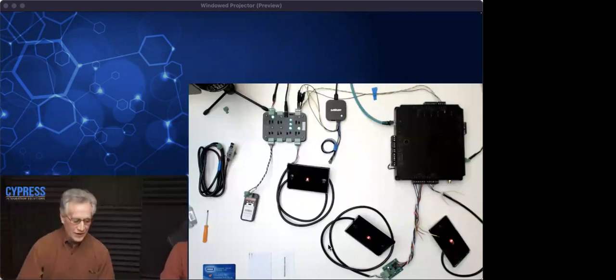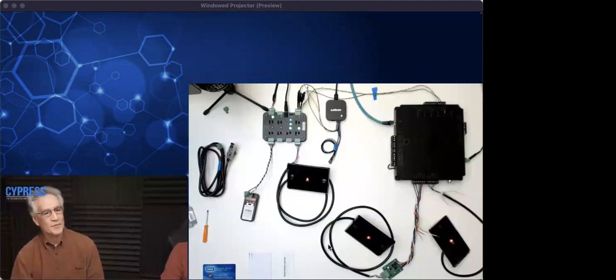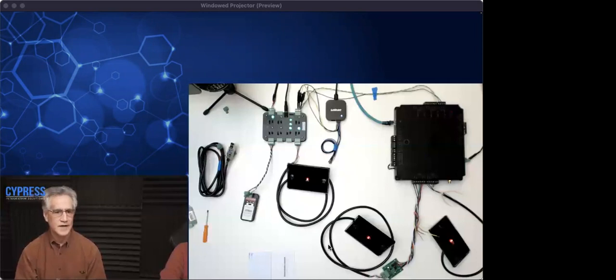Yeah. Okay, so as I mentioned, we have had 4 decades of experience with RS-485 and Wiegand. I know the cable manufacturers hate for me to say this, but essentially Wiegand wire at less than 500 feet is essentially running 9600 baud right now. So the bit pulse widths of Wiegand are more or less equivalent to 9600 baud. So if you want to run that, you had no choice. You had to leave the wire.